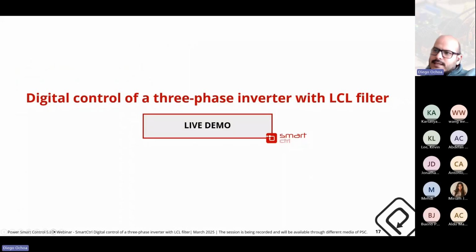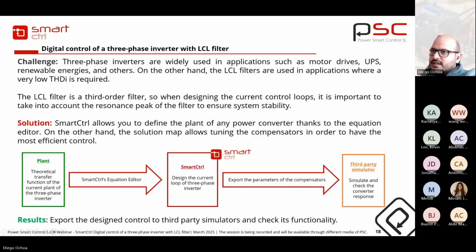So now it's time for the live demo. Today I'm going to show you how to design the digital control of the three-phase inverter with an LCL filter. Three-phase inverters are widely used in applications such as motor drives and renewable energies, etc. And LCL filters are used in applications where very low THD for the current is required.